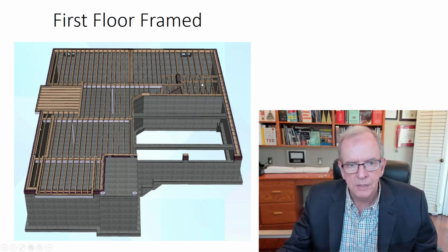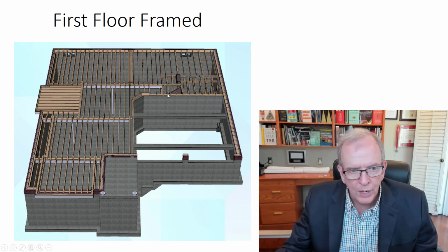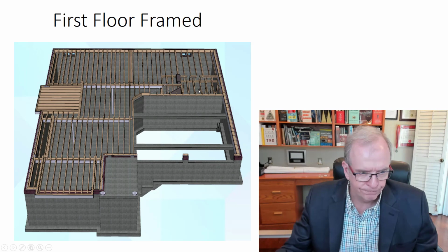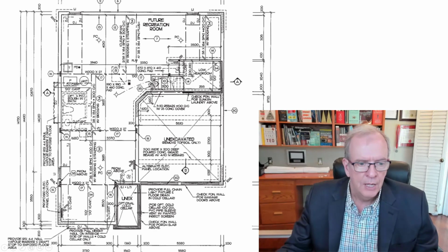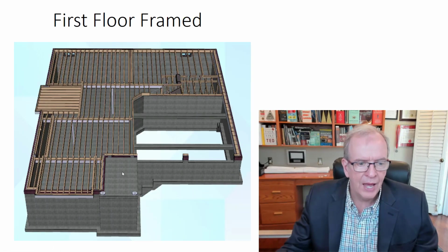So this is basically lower than this. This goes up 2 risers with that stairs. And that's why I said 13 risers all the way up to the first floor, 11 up to the sunken part. And this is that porch slab, which if you remember had sort of an X on the drawings here. That's because it's not on exactly the same level as the floor. The floor is going to be 1 riser higher. And that's where that comes into play, when you have that kind of change and adjustment going on.